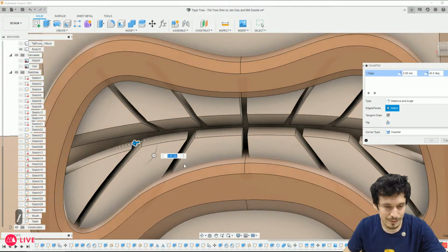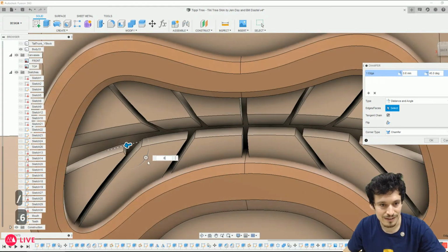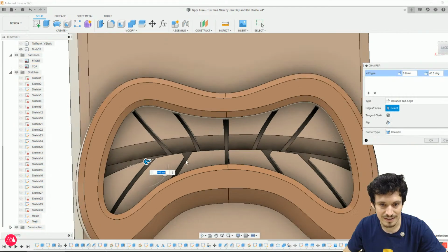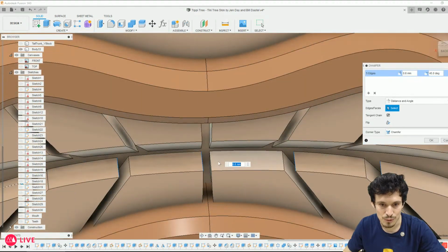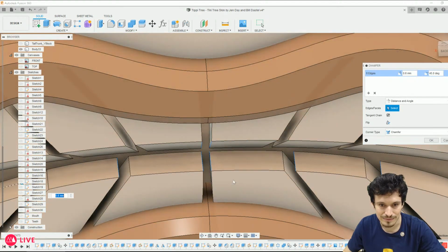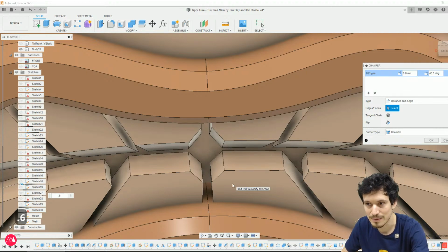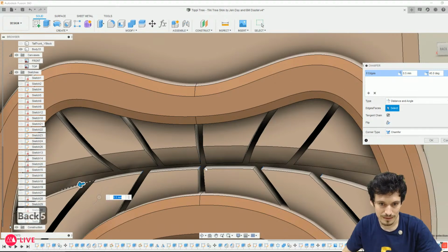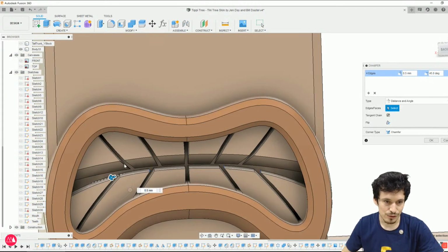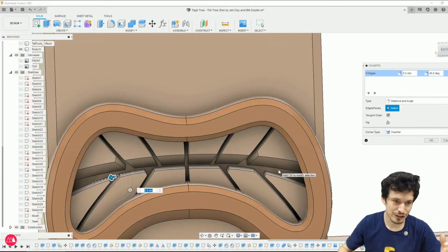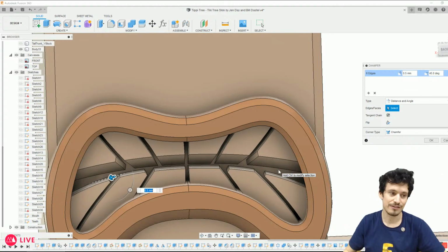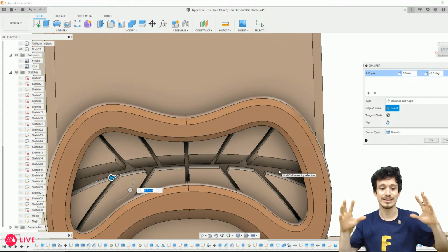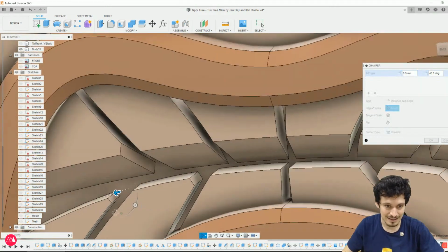So we're gonna do that, and now we're gonna add the smaller chamfers to just kind of get rid of the really pointy bits here. Like that. I think that kind of looks cool, rounding out the teeth just a little bit. Not really rounding, squaring them off is a better word for it. There's a general rule that if you're doing chamfers on top of chamfers or doing fillets and stuff, you usually want to start with the largest ones first, and then you work down to these tiny little ones you're adding.